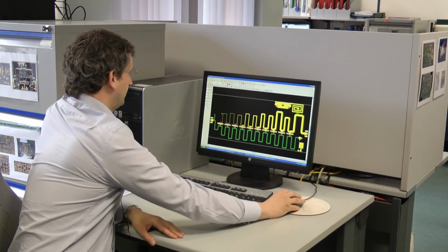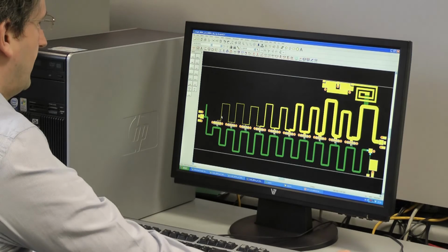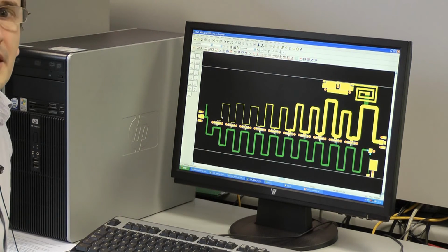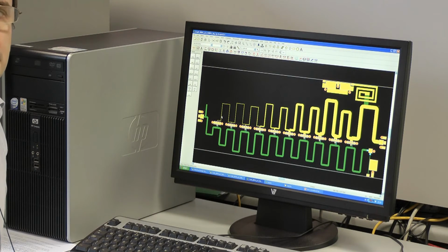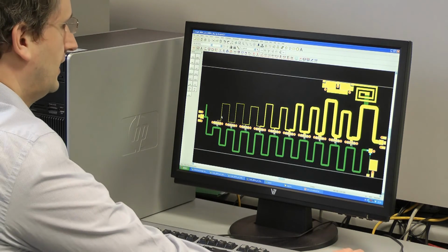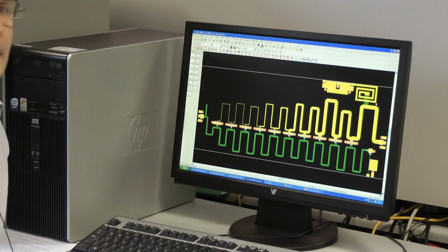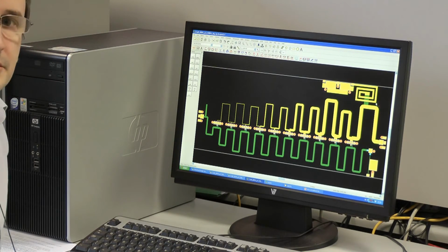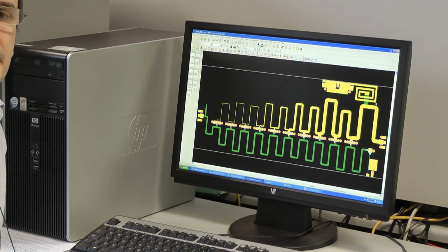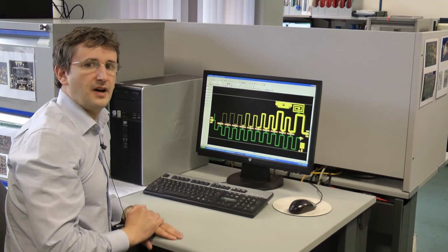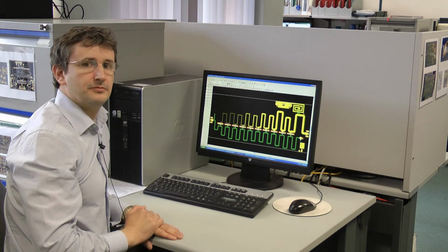As this device is larger than the other 9 devices, this is why our amplifier is a non-uniform distributed amplifier. Care must be taken to ensure that the thin microstrip line can still handle the expected current. Care must also be taken in the design of the drain line bias choke. It must be able to handle the peak drain current, and it must have enough inductance to provide adequate impedance at the bottom of the band.